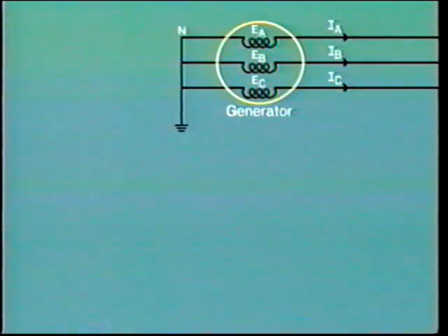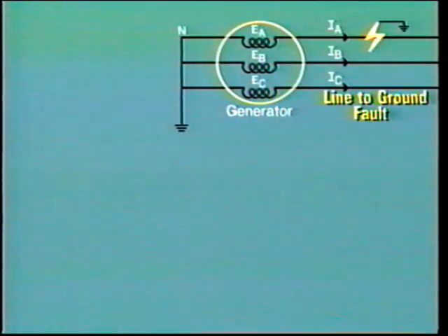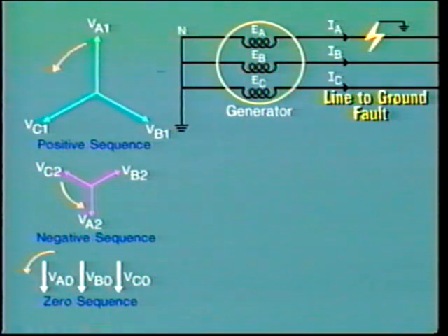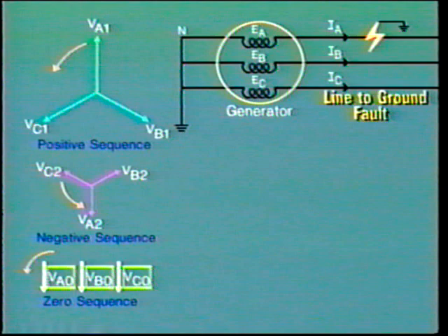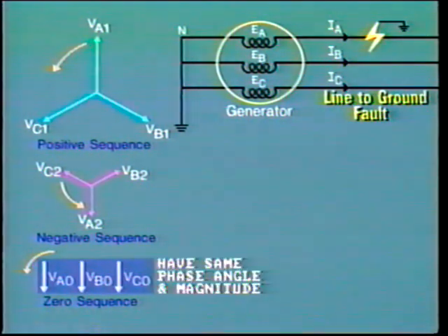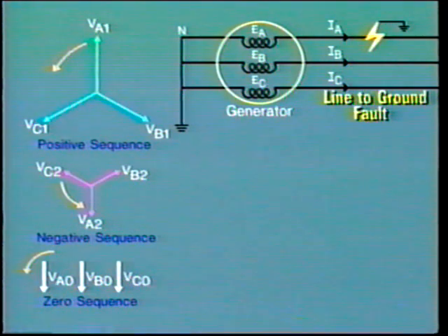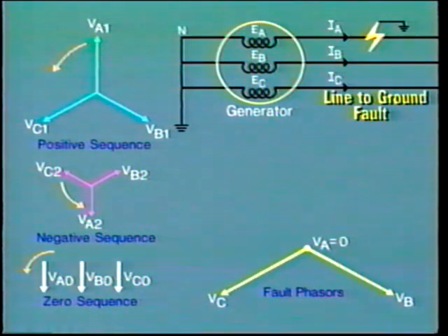So much for a phase-to-phase fault. When there is a ground fault present, we have yet another symmetrical component to deal with. This is known as the zero sequence component because there is no phase angle difference between each phasor. For identification, it is given the subscript 0. In each of the lines, the zero sequence component is at the same phase angle and has the same magnitude. By superimposing the positive, negative, and zero sequence components together, we can derive the phasor representation for this ground fault